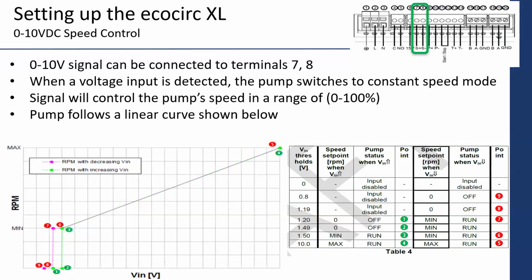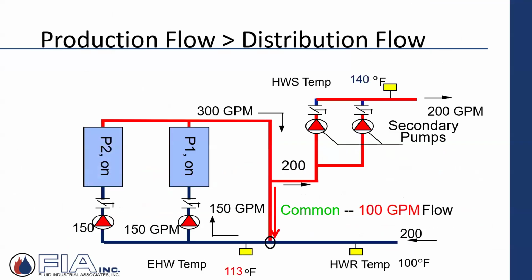So I can start to change flow rates, and we don't need to go through all the exercise at the end of the day here, but what it's all trying to talk about is when you have fixed speed, you can create scenarios where you're over pumping the boiler plant to satisfy, say, a secondary load out in the building's requirements for water temperature.